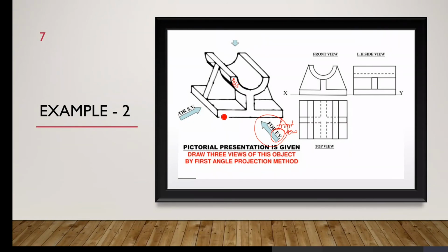So if this is a front view, you can see this surface will be visible, right? And this surface will be visible over here, and this surface will be visible, which you see here. And looking from the front, there is one more surface here which is behind. This is also visible. Why are we drawing this as visible?